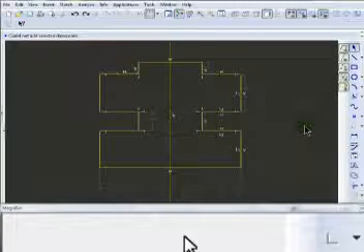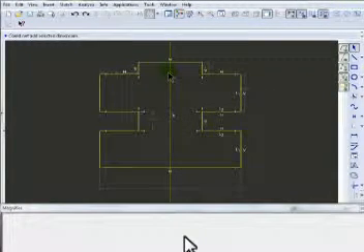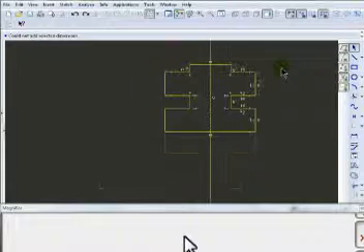The next thing we need to do is to impose the dimensions to match the design intent. Now there are multiple ways of doing this. You could go around and change each dimension individually until you reach the design intent, or there is this other way where you select all the geometry and all the dimensions by dragging a box across it.